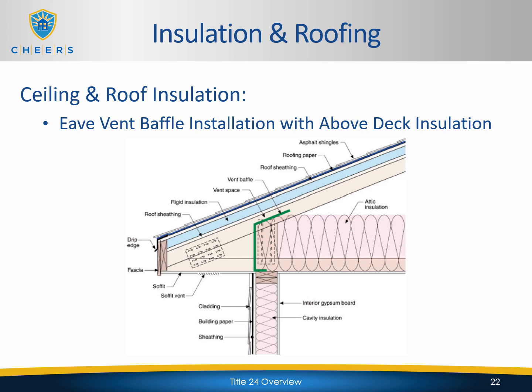Now, the second purpose for it is to prevent air movement into the insulation, or even air movement moving the insulation. If it's loose fill and you have wind blowing in through that vent, it can blow that insulation away, and now you have exposed ceiling to the attic. At the same point, insulation that has air moving freely through it cannot do what it needs to. It will then allow a thermal bypass into the ceiling and increase the ceiling temperature at those areas. So 2 reasons to have those baffles. As you can see in this one, the above deck's not going to be affected by baffles, but we'll look next at the below deck, and you will need to have 2 different types of baffles installed.